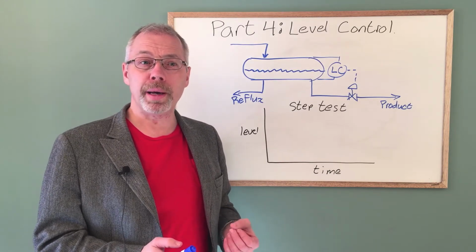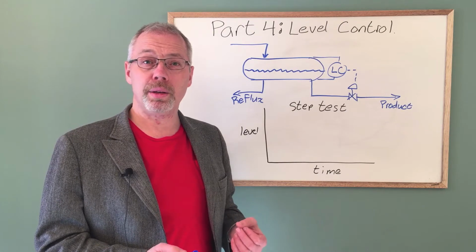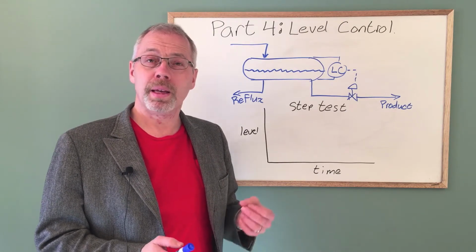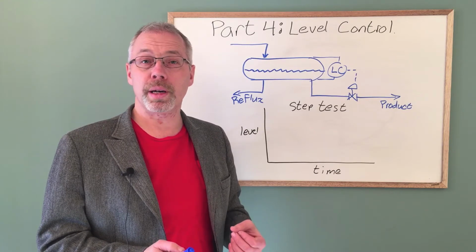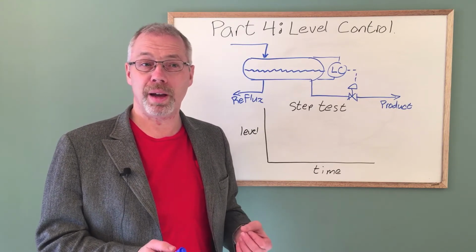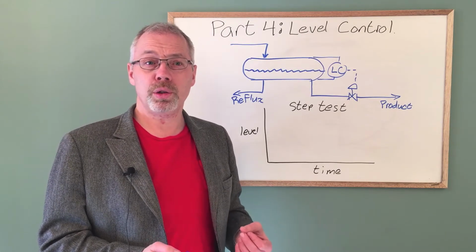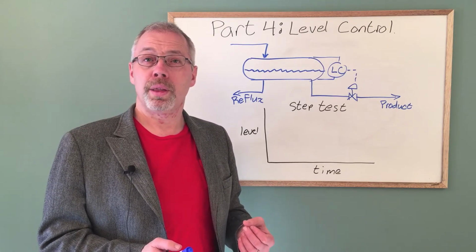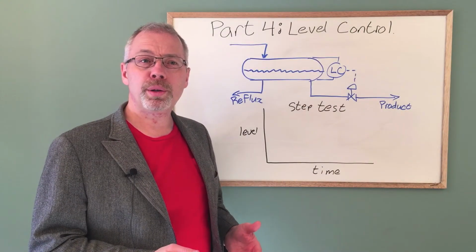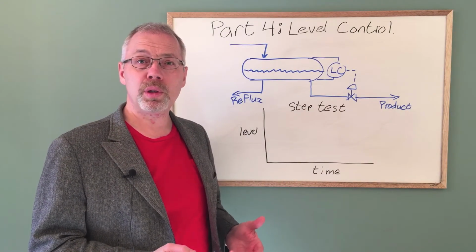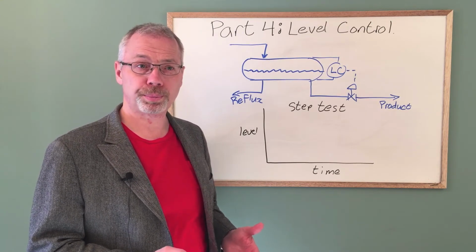We should keep in mind that the objective for level control is not really to maintain the level on set point. Instead, the objective is to provide a smooth flow to the next process, while keeping the level between the allowable limits. A smoothly changing flow is always better than sudden changes to the flow rate. We need to understand how level control behaves in order to determine a good way to tune a PID controller.